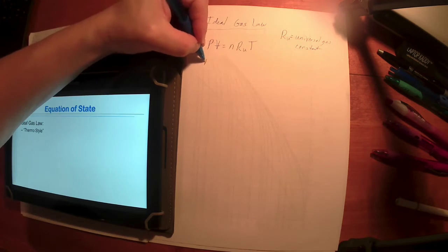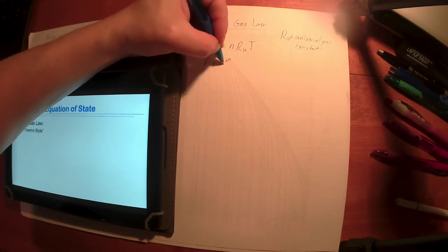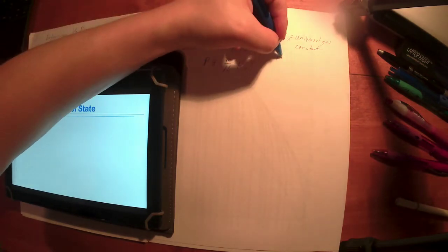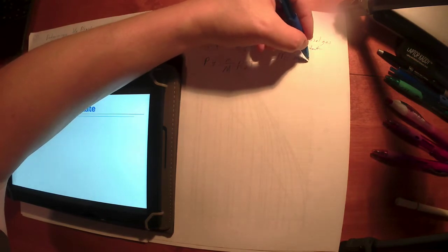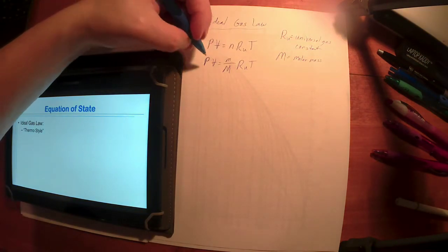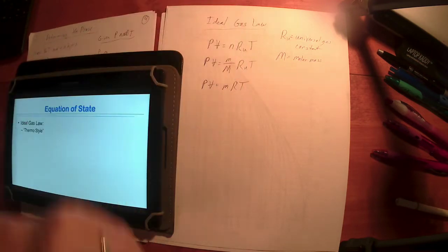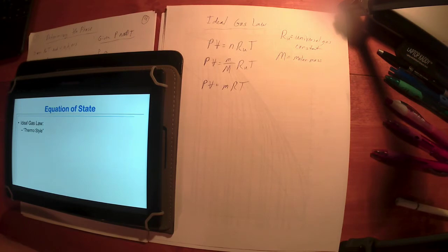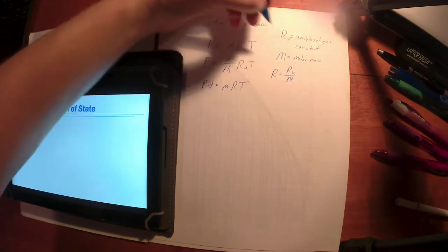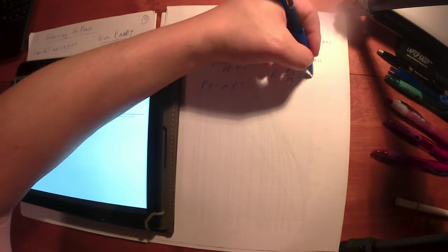And that's where we say, well, remember there is also this form where in chemistry, how do you find the number of moles? Well, you take the mass of your sample divided by the molar or molecular mass. Right? So that's capital M is the molar mass, if you will. Right? And what we normally do with that is say, well, what if we just do this? So what I did there is I said, well, R is the universal gas constant divided by the molar mass for the particular substance, and this, we just call this the gas constant.